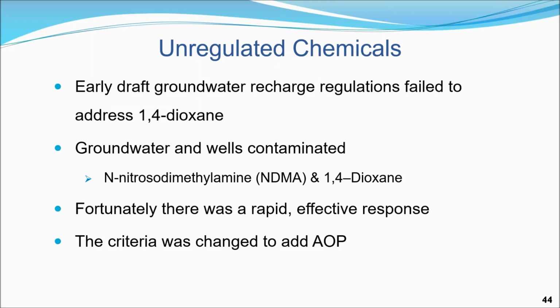Now, I'm going to talk about potable water via groundwater recharge, because that's happening in California and other places in the country, and it's one of the future emerging technologies. It's been done in California for over 50 years, but it wasn't until the 1990s that we realized 1,4-dioxane was detected, and we had early draft groundwater recharge regulations that failed to address 1,4-dioxane.